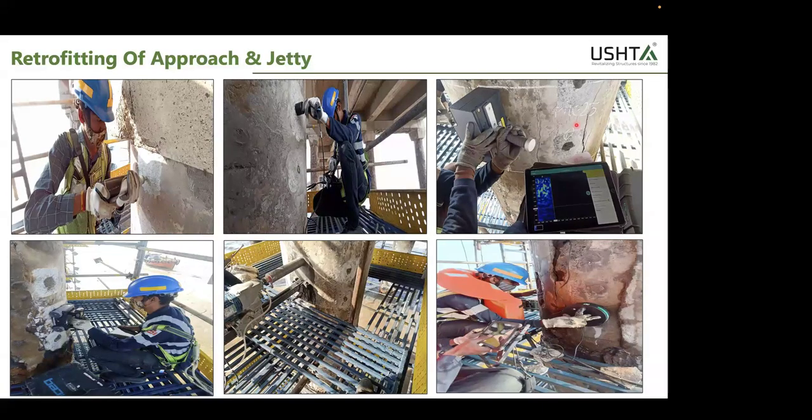So what we did was we conducted some tests on that. That is hammer test, UPV, tomography. So tomography is a much more advanced form of the ultrasonic pulse velocity test. It's like you compare X-ray with CT scan. It'll give you the exact location of voids also.